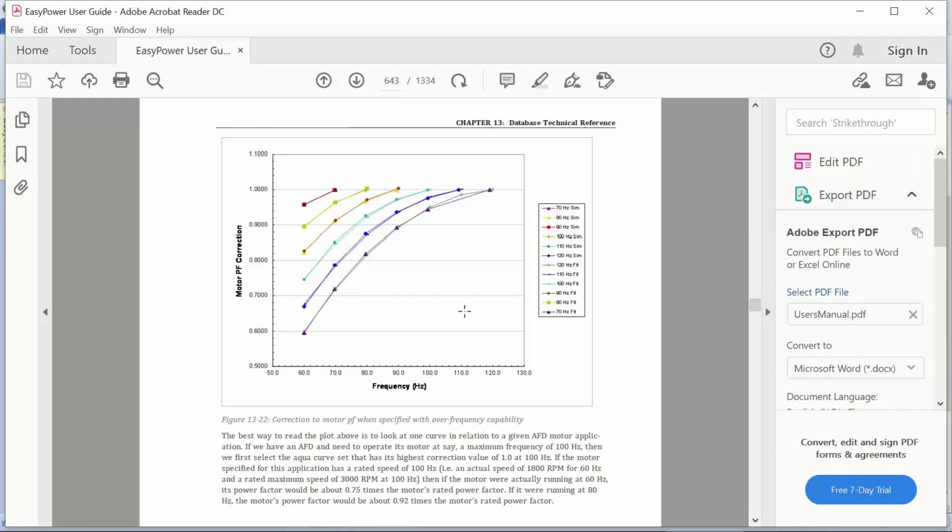Now, so what have we covered? We basically talked about the setup for short circuit. It's fairly straightforward, and the only probable impact of using a VFD drive is the ability to control motor contribution to an upstream fault. In PowerFlow, it gets more complicated, and the tool can handle VFD drives at pushing a motor to a different frequency.